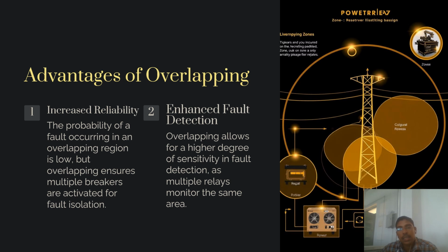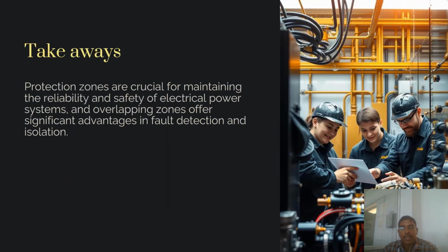Another is enhanced fault detection, which means it gives more precision in fault detection with respect to multiple relays working on the particular zone. So these are some major things concerning the zones of protection. These are the possible takeaways from this one. It is going to make the system safest if you are providing the overlapping.